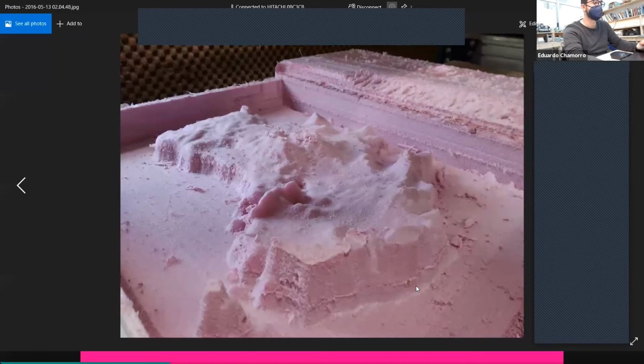For example, this is an awful cut made in climb. If you had made this in conventional, you would get, for example, the quality of the map that you saw there. This is foam. The whole Barcelona map there is foam, cut in conventional. And you can choose the best end mill, just an end mill for foam. It doesn't matter. If you cut in climb, you will get a awful result. You cut with conventional, you will get awesome results. As easy as just changing the technique.